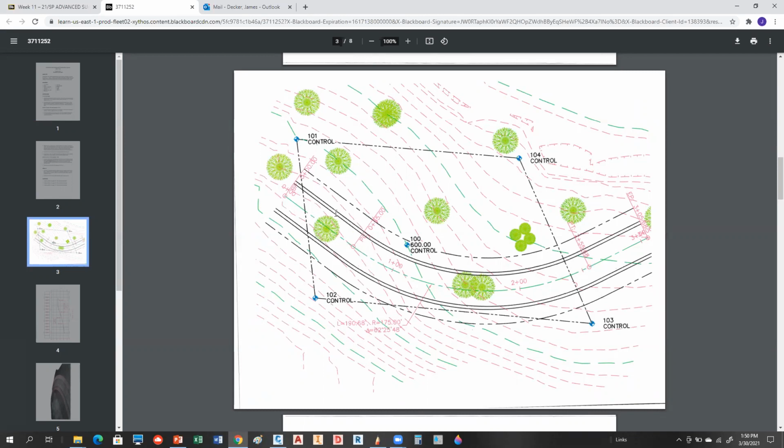We're going to put the tangent points in this way, and we're going to deflect around this curve into the PT. So I'm going to have one group that's going to do that on the inside side of the pavement, one group on the outside side of the pavement, and one group on the center line. Okay, so this is your curve that you're going to lay out.